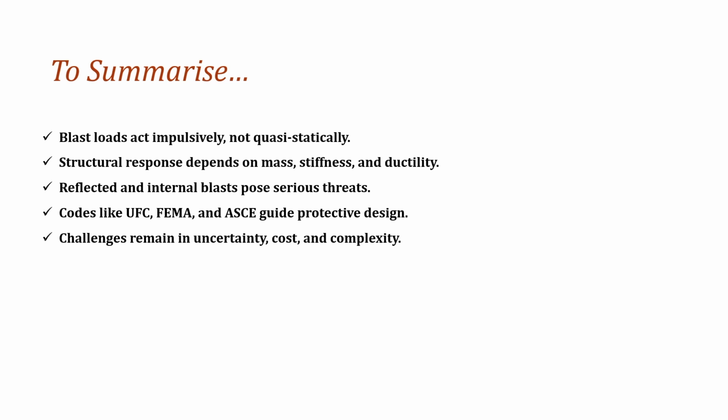The research covering UFC, FEMA, ASCE and the IS code gives us some insight into how to design for this, but there is a long way to go, including incorporating different types of performance based design, taking into account the response from the non-structural elements, giving a holistic view depending upon the risk assessment and the risk mitigation effects. So, we have a very long way to go to properly issue protective design codes against the blast event.